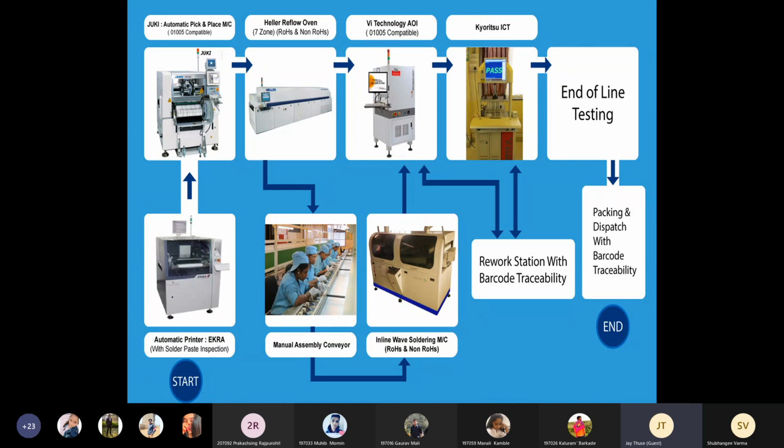As I was explaining in the last slide, in electronic assemblies you have SMD components, which are very small in size, and leaded or through-hole components, which are pretty large. SMD components can't really be placed by hand. You can't hand solder them, and you can't say, "Hey, this is my PCB, assemble those components by hand soldering."